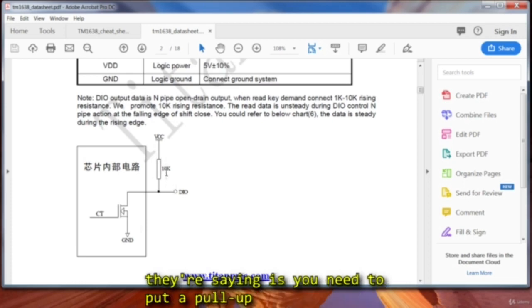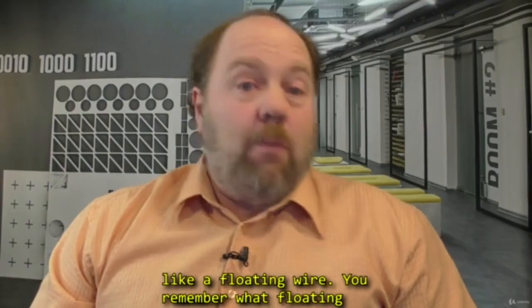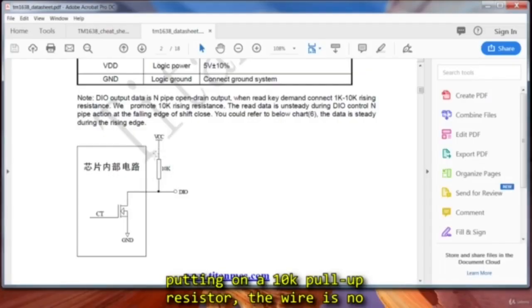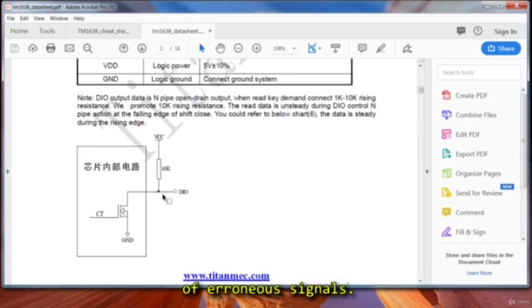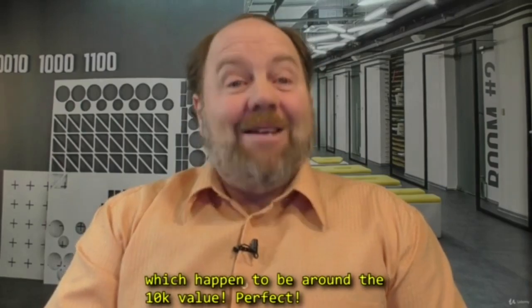So basically what they're saying is you need a pull-up resistor on the DIO line when you are receiving data on it. The reason is they use a MOSFET on the output, which has such a high resistance when it's off that the DIO line will be like a floating wire. And you remember what floating wires did on our very high input impedance digital inputs: they were so sensitive that they would pick up induced electrical noise. So by putting on a 10K pull-up resistor, the wire is no longer floating, but held high to get rid of erroneous signals. Conveniently, on both the PIC and Arduino, we have the option of using internal pull-up resistors, which happen to be around the 10K value.